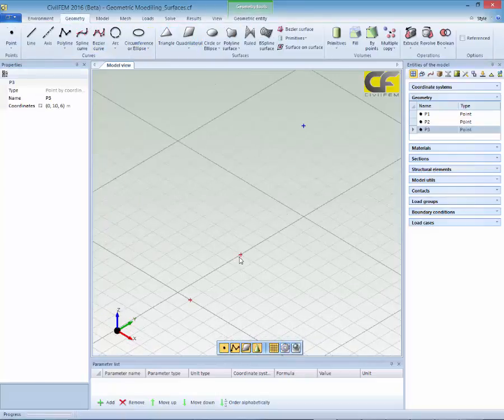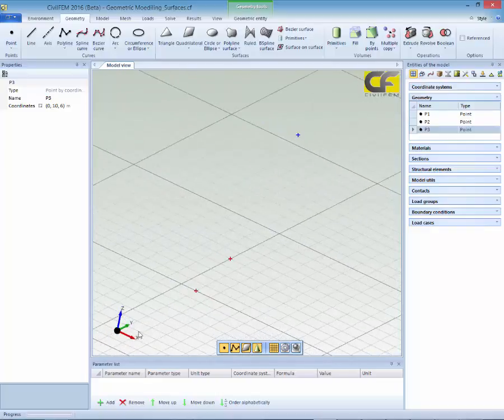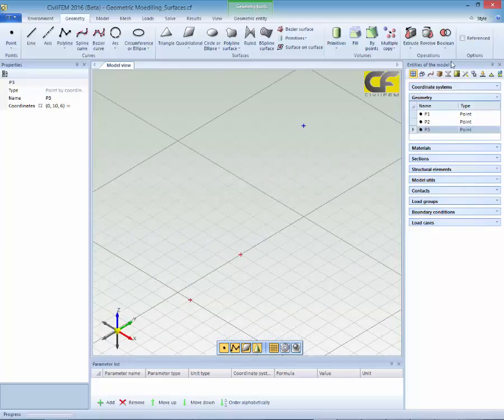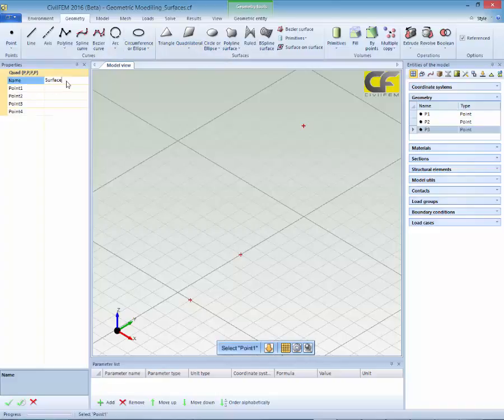We have defined these points, and we check the reference option, select quadrilateral 4 points, and now we have surface 1, for example. In the name we have these cells for defining these points. So instead of introducing point by point as we did before, now for the surfaces we can do it only by selecting the points that we have to add.